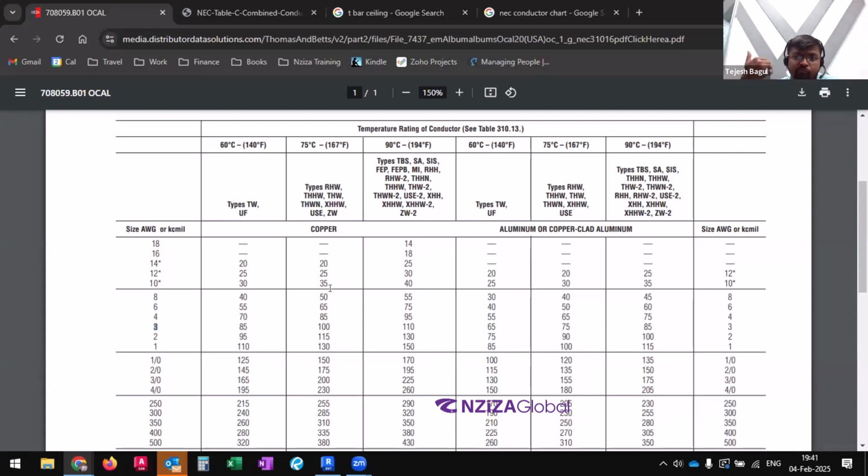Underground conduit will have moisture, might also have loads going over it, and so forth. So the underground conduit tends to be more rigid, more able to absorb the stress and strain of the earth as well as the loads, along with being water resistant and watertight, not letting water go into the conduit. That is what I'm trying to say.